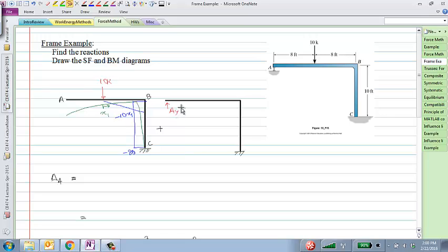And for AY, actually I should do that. AY times this structure where I apply a unit load there. So if I apply a unit load there and take whatever response I get from that right hand side substructure, multiply that response by the unknown redundant force AY, then add it to the original determinate system, then the sum of these two should be equal to my indeterminate problem. And that's the logic here.